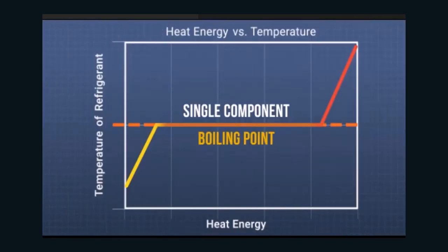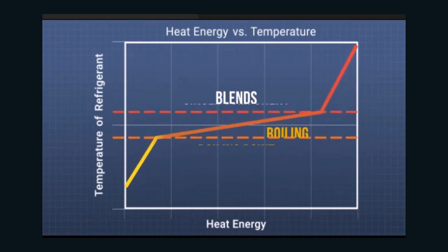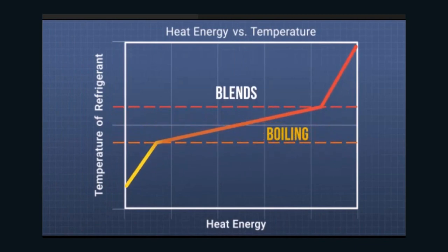400 and 500 series refrigerant blends separate, or fractionate, during the refrigeration cycle because the different refrigerants have different boiling points. This leads to multiple vaporization points referred to as temperature glide, among other things.